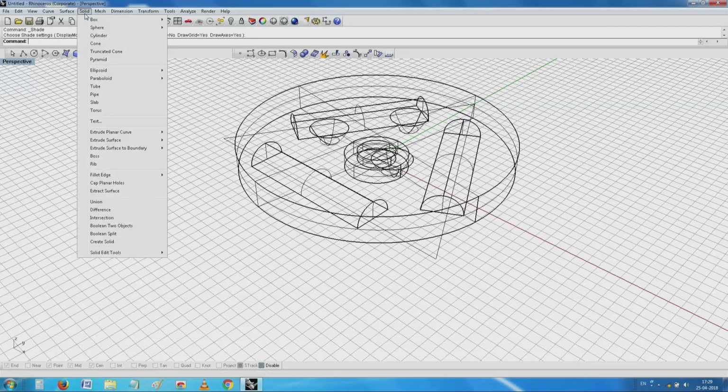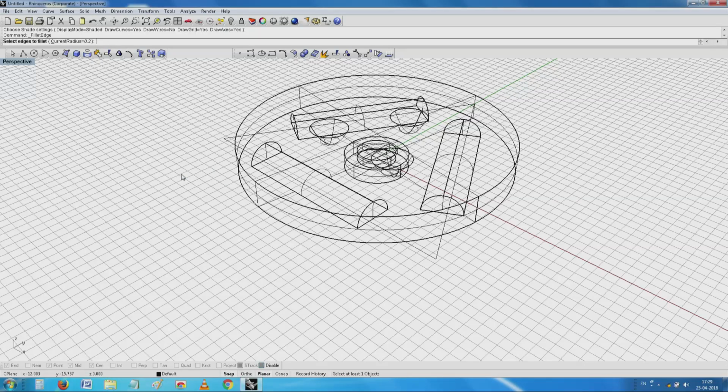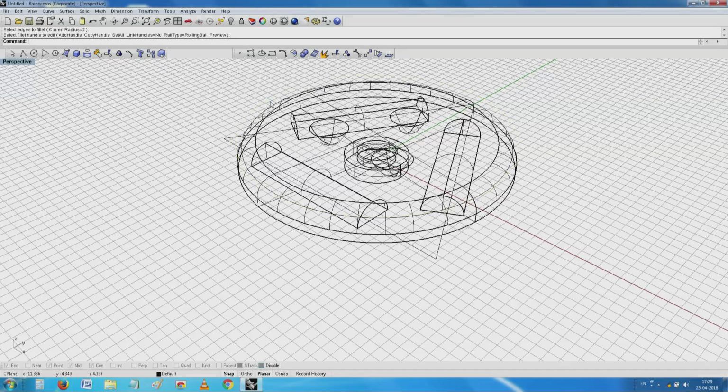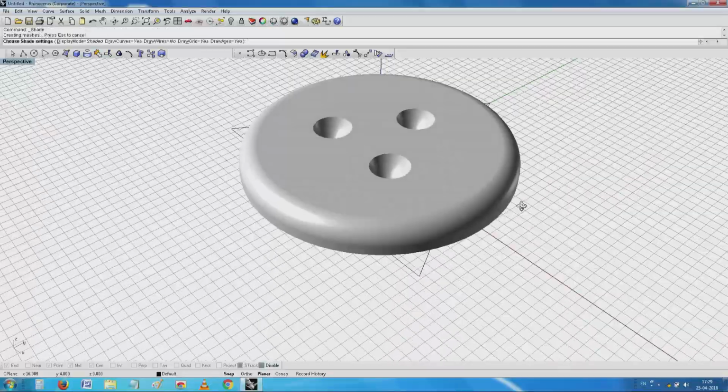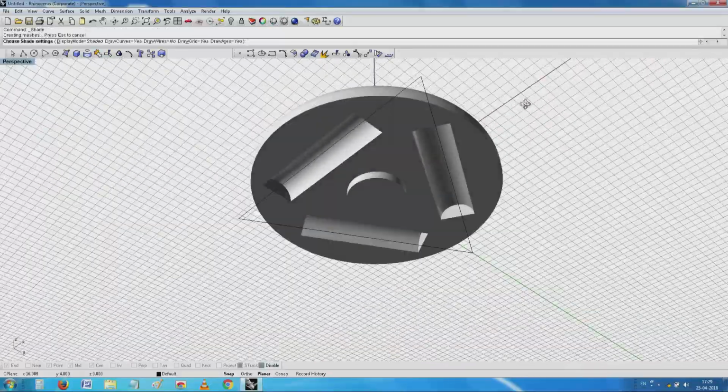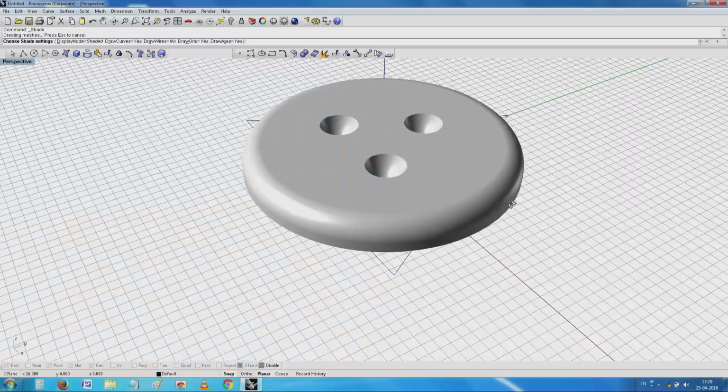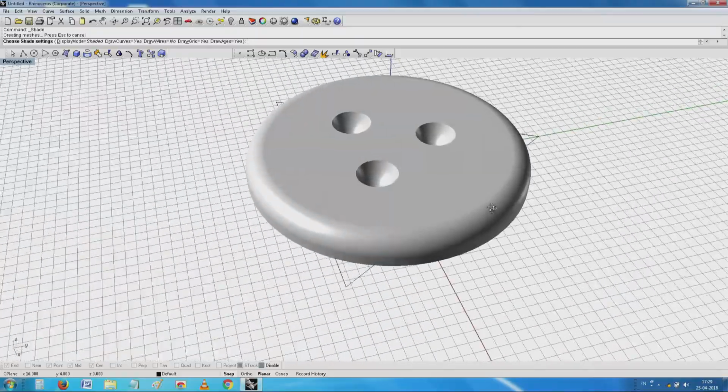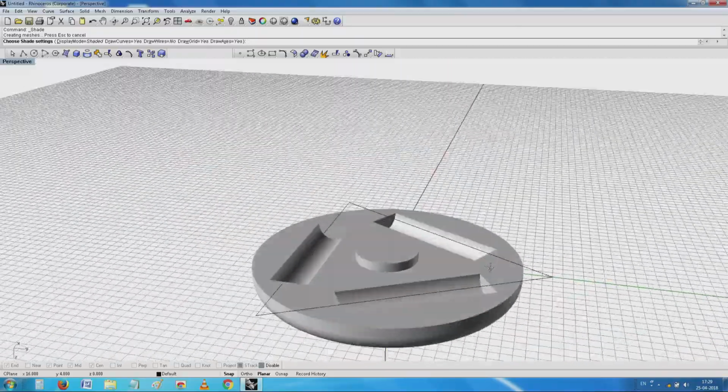I am sorry, supposing enough material is there, I can keep playing with the fillet. That 1 mm was too small, I am sorry, I will give a 2 mm fillet and see what will happen. You have seen this, much more presentable, a dice like object has started there. Seen this, I have all the elements that I want.